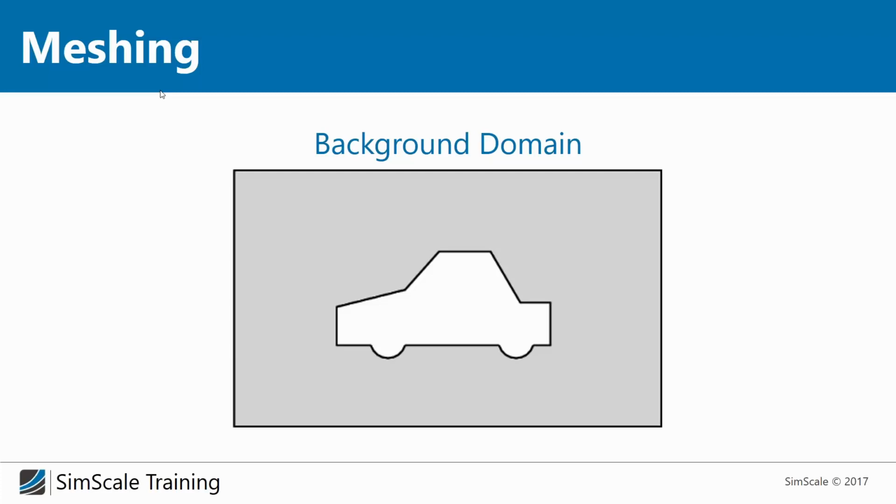And usually meshing is really a big mess because you have an approach where you start to mesh, first of all, only the edges, then based on the mesh of your edges, you mesh the surfaces and then the volume, which can take a lot of time. But with SnappyHexMesh, we have a different approach, which is much more straightforward. This approach is about taking a mesh, morphing it, and adapting it to the geometry you're interested in.